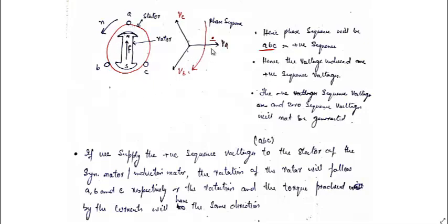Same phase sequence is shown in the phasor form, because you can see that it rotates in this direction. All the phasors will rotate in this direction because phasors are rotating in nature. If someone sits here, let's say at this dot, you can see that all the phasors will rotate. First it will see phase A, and then it will see phase B, and it will see phase C, because they will rotate like this. So that's how we can say this is the phase sequence. Hence its phase sequence will be A, B, C, which we can conclude is the positive sequence phase.